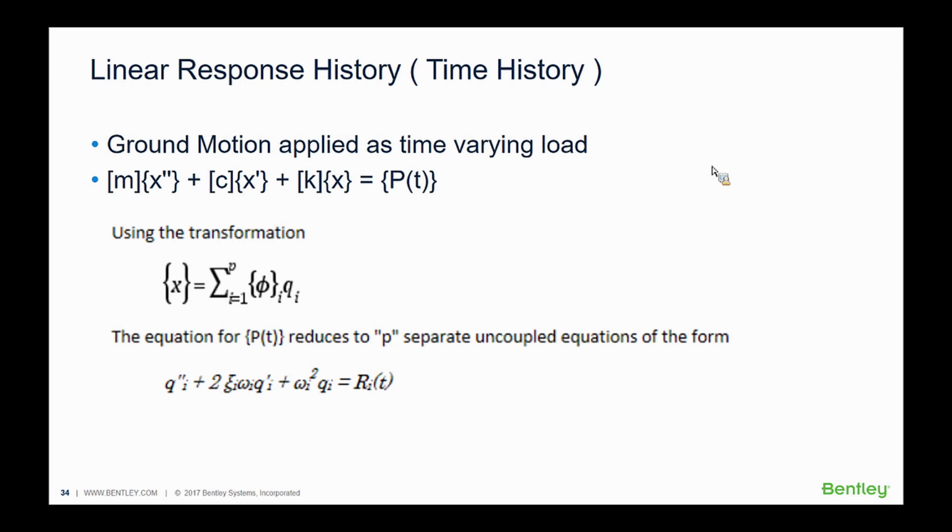What we see here is the basic equation of motion, which is a differential equation where the variables are coupled. The analysis is performed using the modal superposition, where it is assumed that the structural response is obtained from the P lowest modes. The coupled equations are uncoupled and displacements are solved at each time instant.